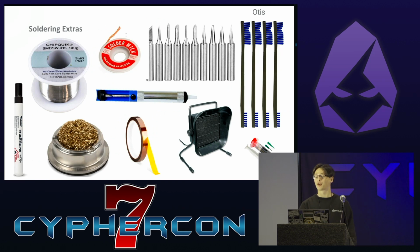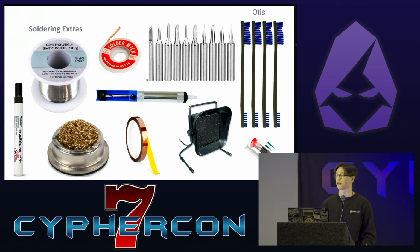Soldering extras. For solder, I like to get a couple different thicknesses. I like to have a thicker one for through-hole parts where I'm putting down more solder and just want to get it down quickly. But then also a thinner diameter, so you get a little bit finer control over how much solder you're dispensing at once for some of those smaller surface mount parts.